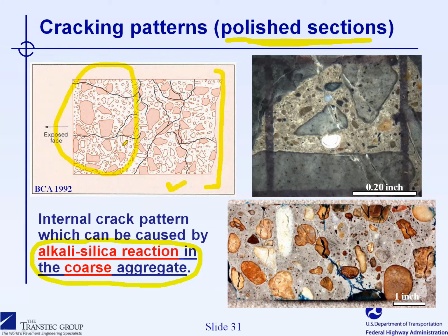So you have macro crack present at the surface of the concrete element. Those macro cracks are generally related to differences in the moisture condition between the surface or the skin of the concrete and the internal portion of the concrete, where micro cracks will be more developed than at the surface of the affected concrete.